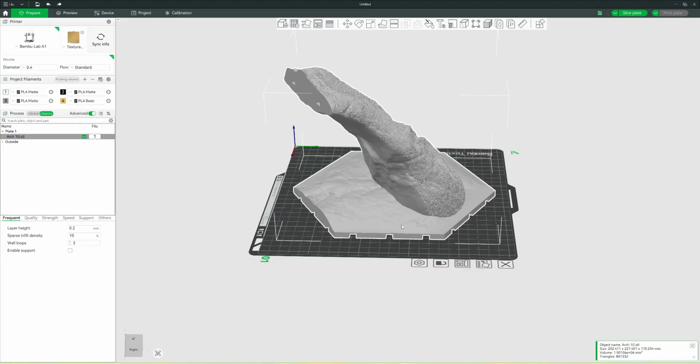So now what we want to do is select just the bottom 6 millimeters of this base and change that to another kind of infill pattern. That way we can get a little more strength around the pins and just a stronger base in general.